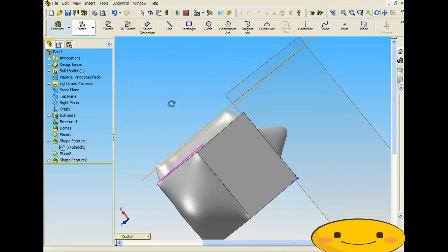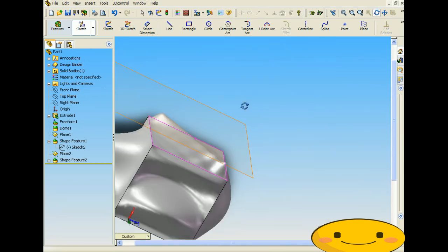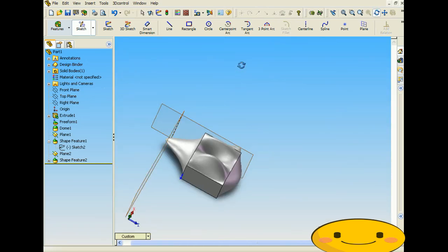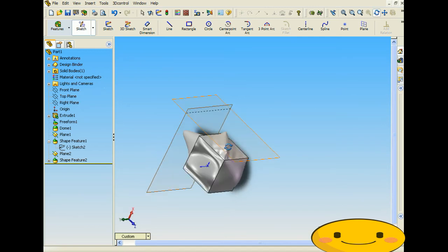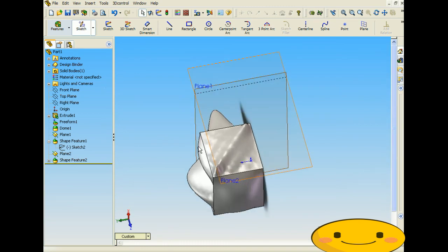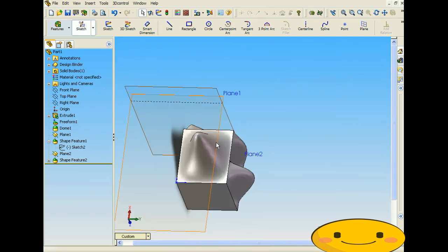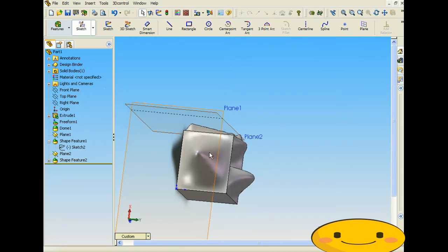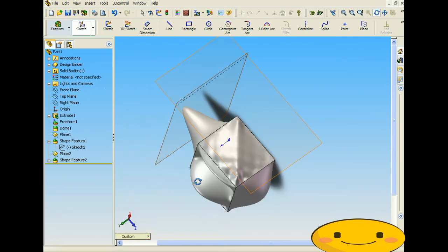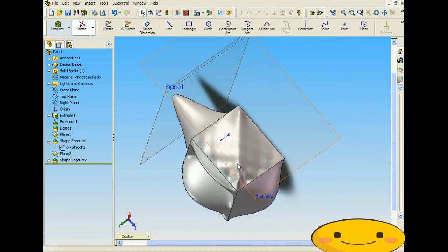And the shape and the feature, it's going to follow it again. So with this tool, if you make a sketch that's on a plane or another surface that's away from the face that you're going to be using, you're able to manipulate what kind of form or shape is going to come out of there, and it's going to look like your sketch. So in this case, we used a circle in the middle, and it comes up and it goes to that circle. In this case here, we use a diagonal line. It's going to come up like a diagonal line going across there.